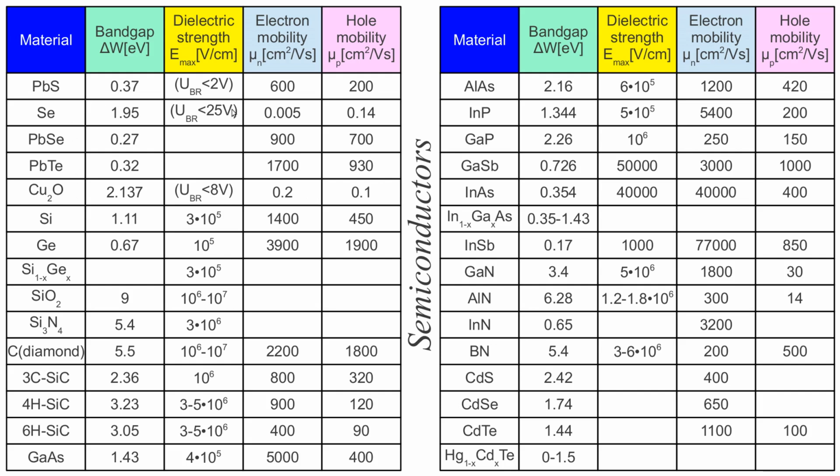Some semiconductors were used in the past, like selenium. Selenium rectifiers were used in the past for mains frequency 50 Hz or 60 Hz rectifiers, but they are very slow. They have very low electron and hole mobilities, so only very slow diodes can be made out of selenium. Some compounds like lead selenide and lead telluride were used as photodetectors. Talking about photodetectors, we also used other compounds like cadmium sulfide, cadmium selenide, cadmium telluride. This was all used to build photoresistors.